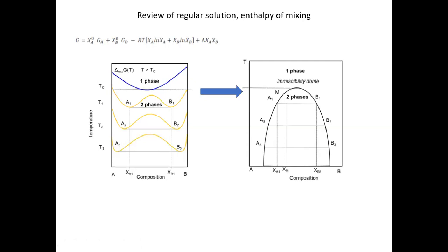Okay. So again, this is the thermodynamics of spinodal decomposition, right? You start with a regular solution, and you have a competition between entropy and enthalpy. When temperature decreases, the enthalpy is going to dominate, and you begin to develop two local minima on the free energy curve.